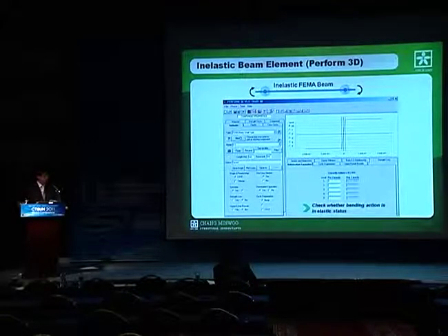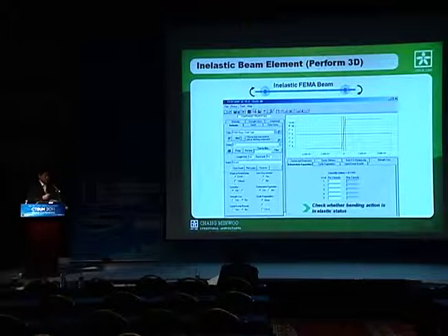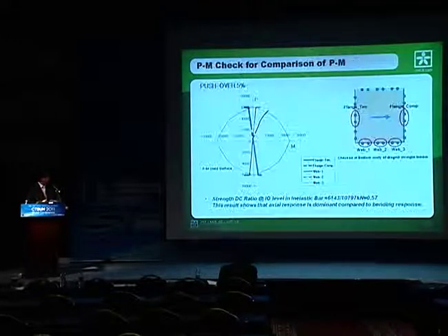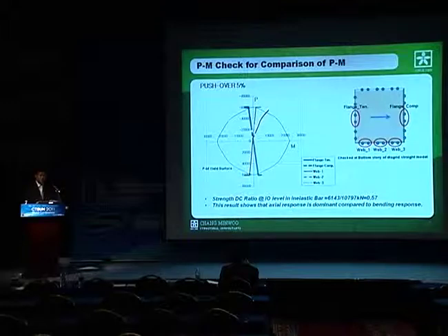And this is for the inelastic beam, so it's very familiar to you. A beam element was also added to the same member, but when modeling this, the purpose of adding it is only monitoring the flexural behavior. We also conducted a PM interaction check for comparison of axial force and the moment history in Diagrid members at the lower levels. So this is the result from the pushover analysis.